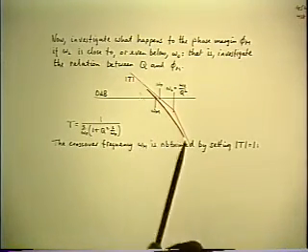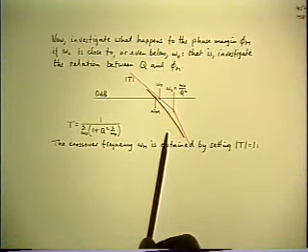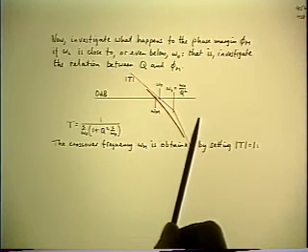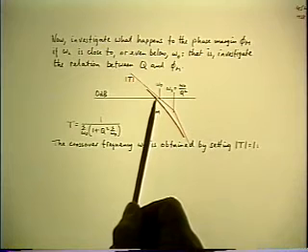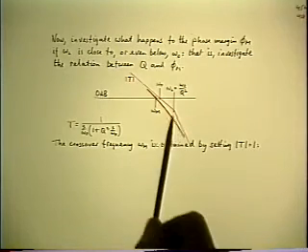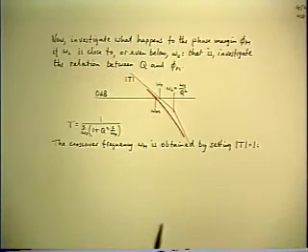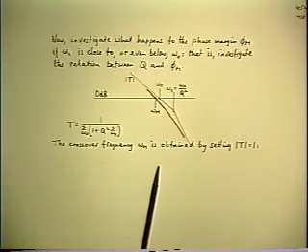In other words, the smooth corner is going to move through the axis, and the crossover frequency is really the frequency where the actual curve crosses unity magnitude, not where the asymptote crosses. So omega m is the true crossover frequency at which we want to evaluate the phase margin.